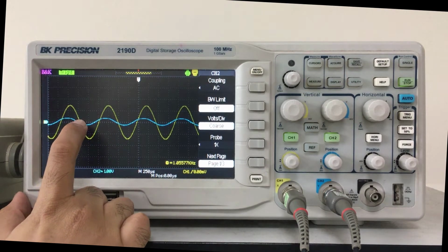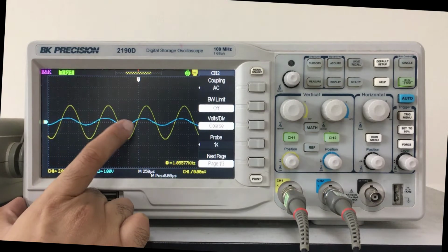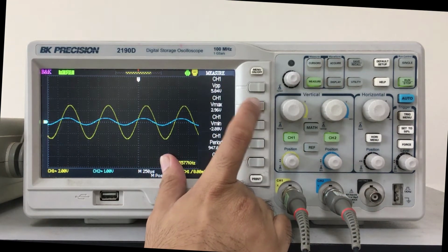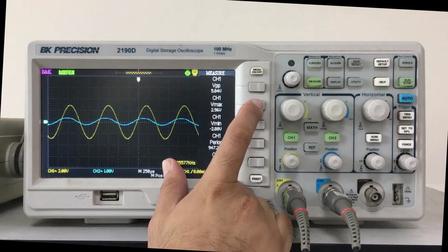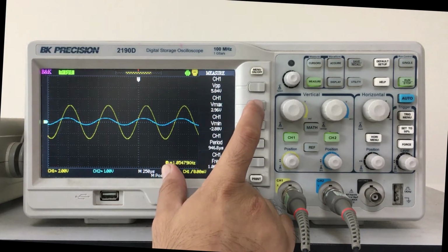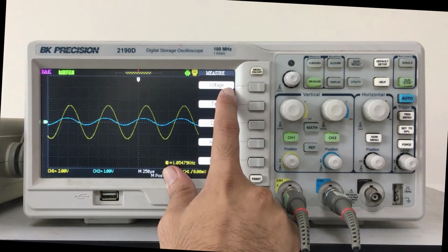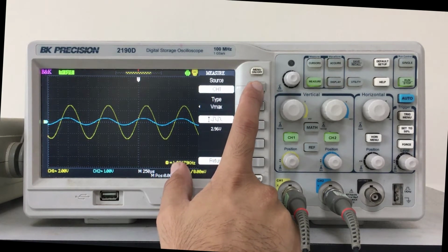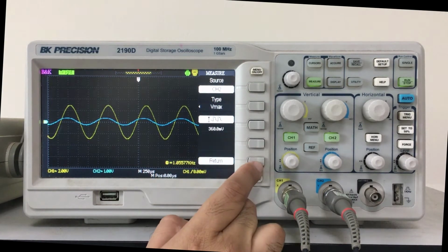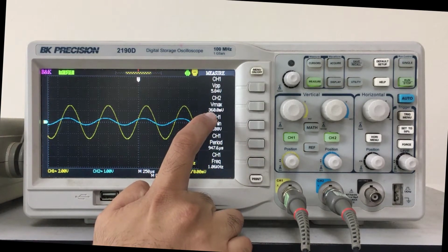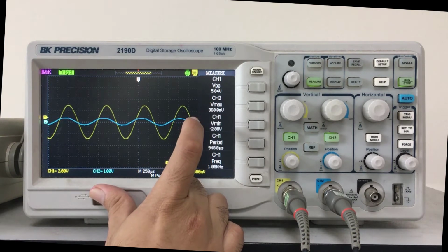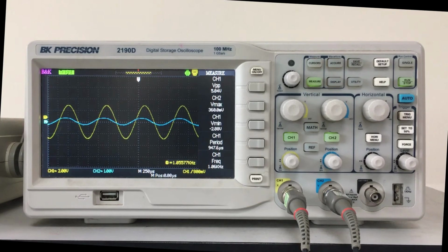So channel 2 is connected to node B. Channel 2 is giving us the voltage waveform of RS source. So if we go to measure and place channel 2 Vmax in this box, it's your choice which box you choose. I'm choosing this one, and since we're going to take a reading of a voltage, the category is voltage, source should be changed to channel 2. So if I press return, channel 2 Vmax is 360 millivolt. So 360 millivolt is the peak voltage of RS source, and we should record that in our table.